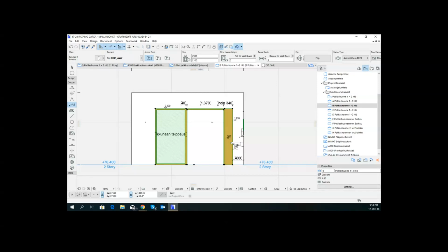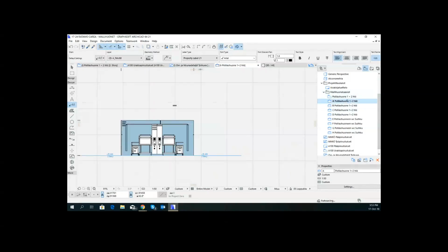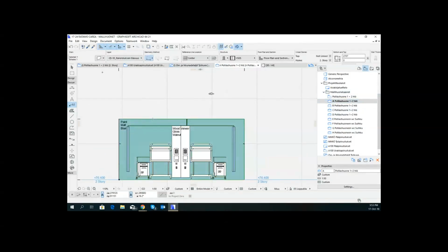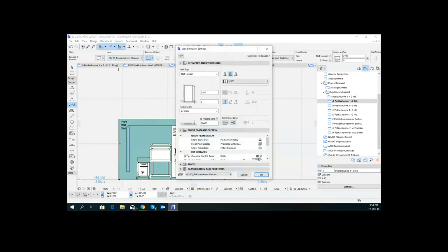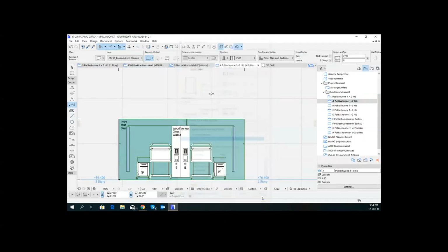So if we go from there, we can also then come back to that other view, like over here. And I've just had a play around here. I've set up some properties for these walls. So I've set up things like a finish type, a colour, gloss level, RAL code, the manufacturer, and the application method that will relate to walls.